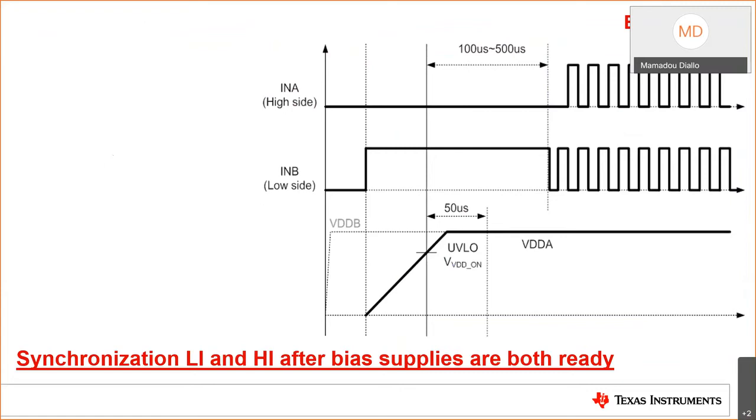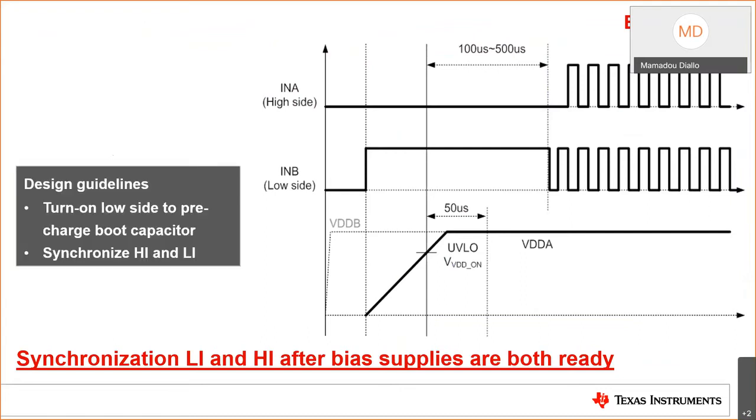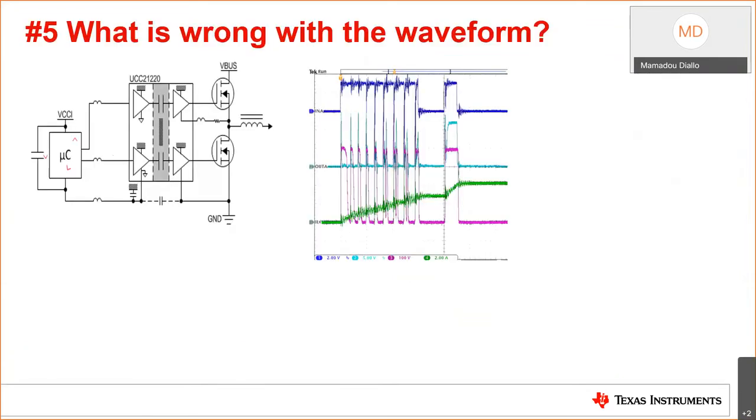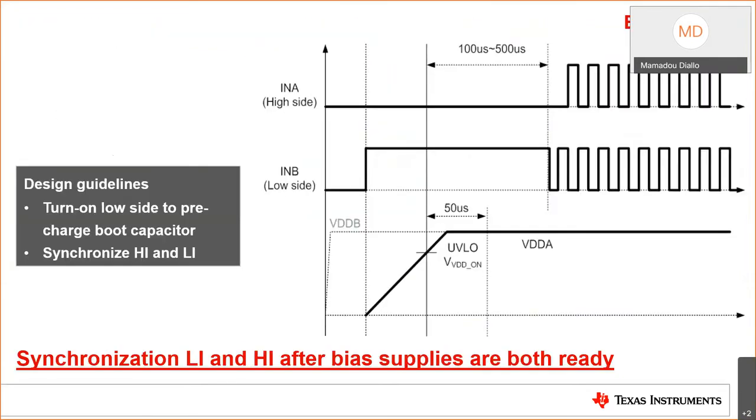So before the driver is ready to deliver proper output state, there is a power up delay from the UVLO rising edge to output. This delay varies according to the driver. This may be as high as 50 microseconds for some drivers. It is therefore recommended to consider proper margin before launching the PWM signal.